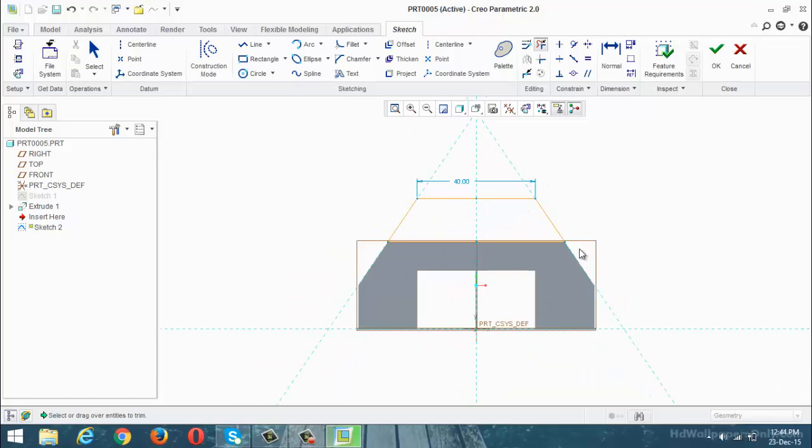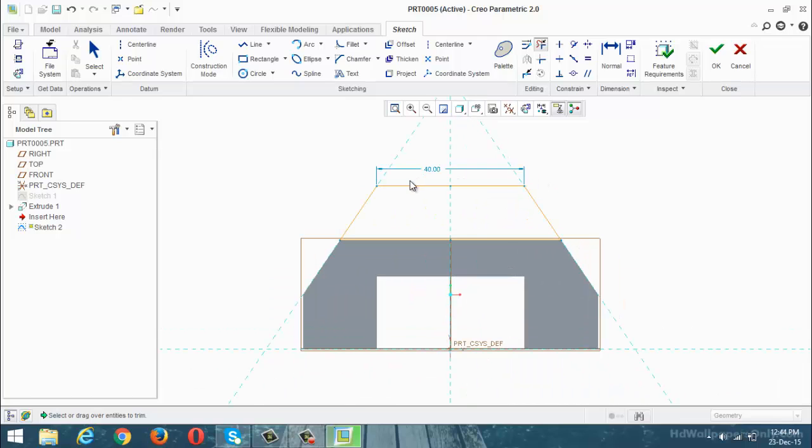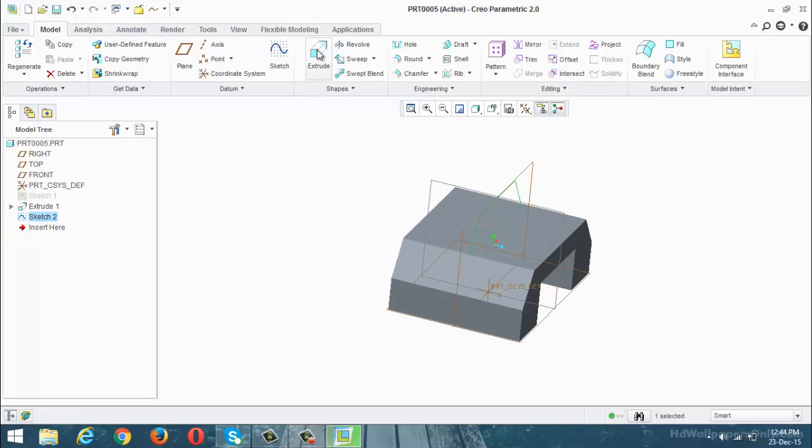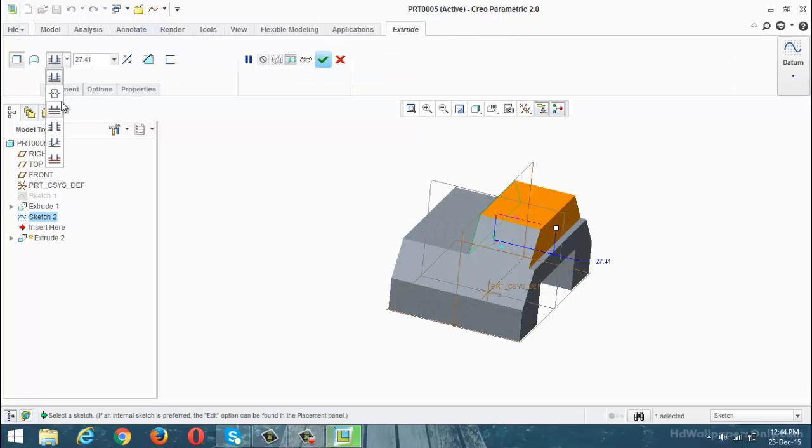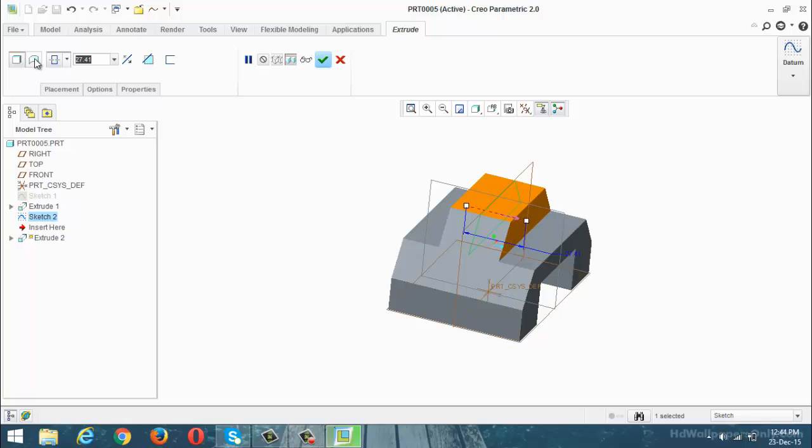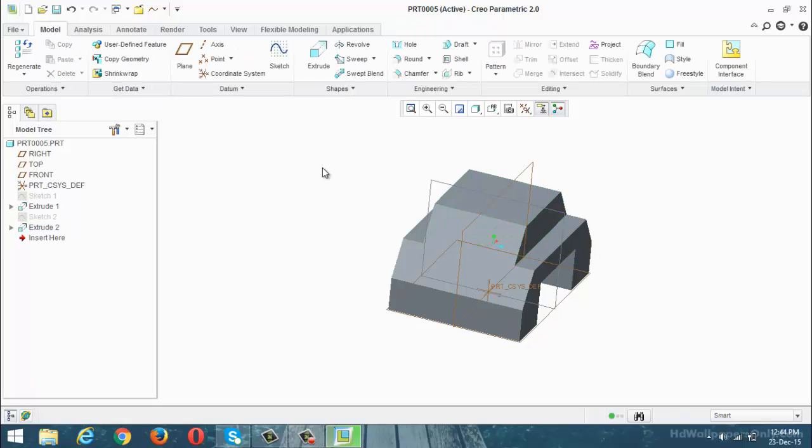Okay na? Now sometimes this dimension is not there, directly the value is there. Now this is the procedure. First you can activate references, project this one, again design the lines. Okay, then again you can apply the extrude. How much? Place the symmetrical 42. Just okay.